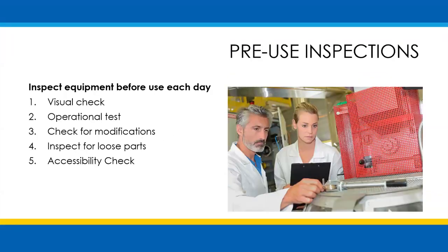Have employees that use guarded equipment conduct pre-use inspections before they use the equipment each day. These inspections may include a visual check, an operational test, checking for modifications or bypasses to the guards, inspecting for loose parts, ensuring guards do not make equipment inaccessible or more dangerous to use.